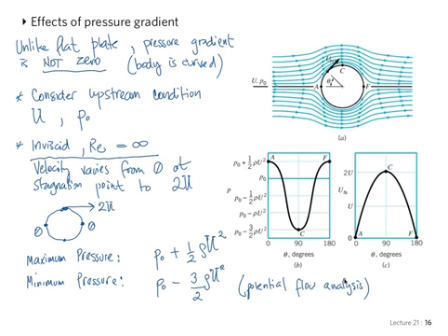Potential flow is the branch of fluid mechanics that is dedicated to inviscid and irrotational flow, fluid that doesn't have any vortices in it. And we don't cover that in this course. Because the flow cannot go through the body, right? So there's still the no-through boundary condition, despite the fact that we don't require the no-slip boundary condition to be satisfied. There is a slip velocity, and we don't care.